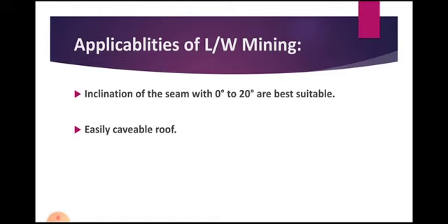And next, this method is applicable for the seams which are oriented with a slight inclination of 0 degrees to 20 degrees. 0 degrees is nothing but an almost flat or horizontal coal bed deposit, and a slight inclination of up to 20 degrees is acceptable to use this longwall mining method.